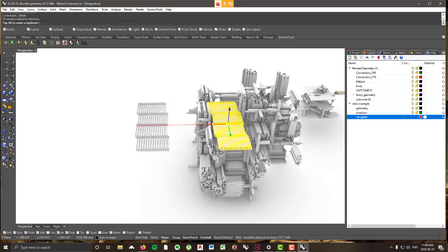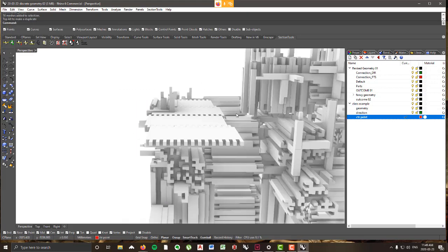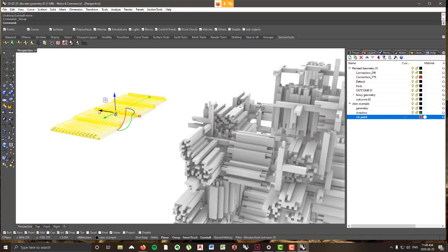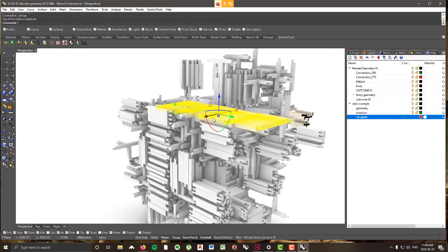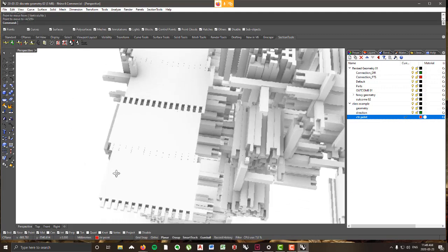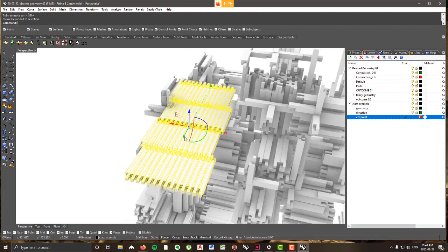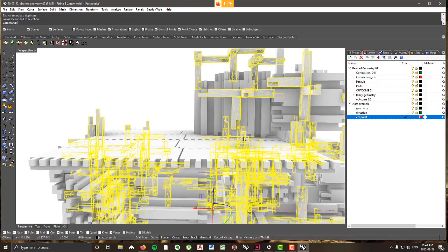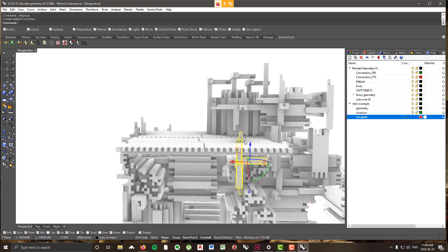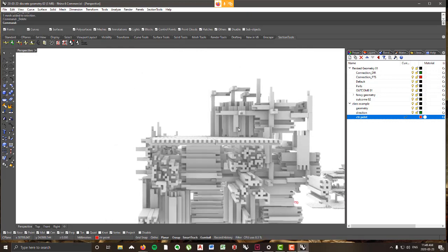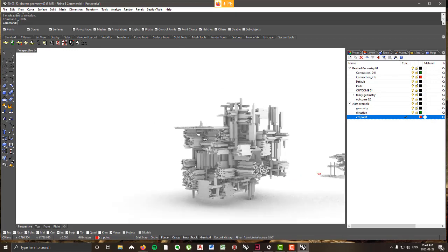Instead, what I'd like to see you do is kind of selectively take maybe a floor piece like this. I'll just group this. Move it more accurately so it actually fits within your overall system. So in other words, transform move, make sure you're snapping vertices to vertices. And then, you know, start moving this around, copying and pasting it. And then maybe start deleting some stuff, like, I'll ungroup that, maybe say that's not needed. So there we go. There's our viewing platform, but we also have this cool sculptural component.